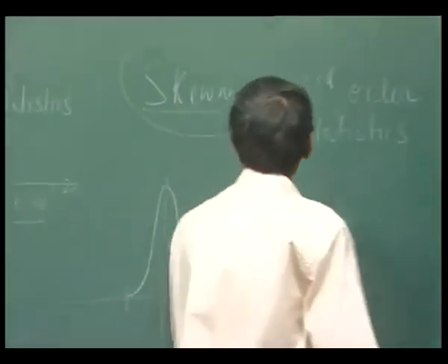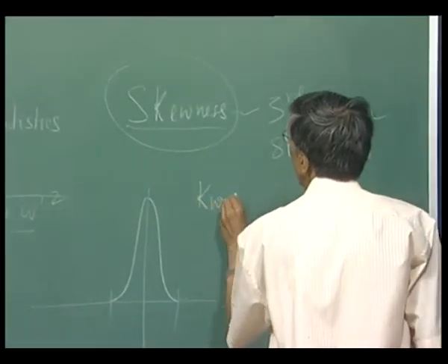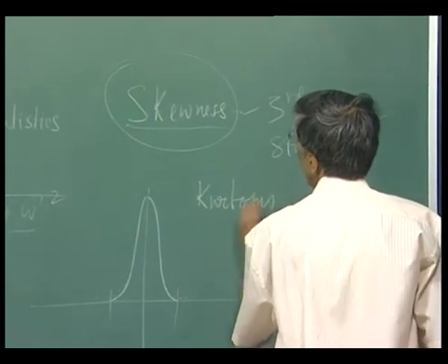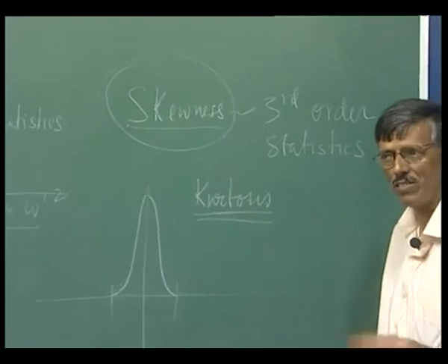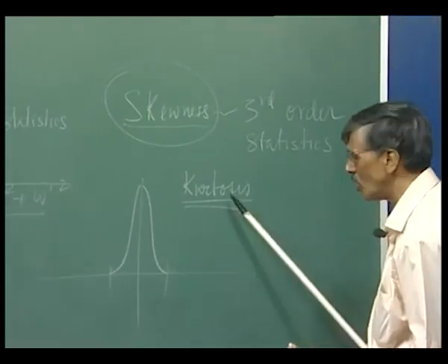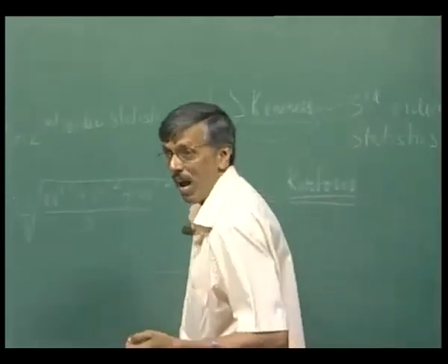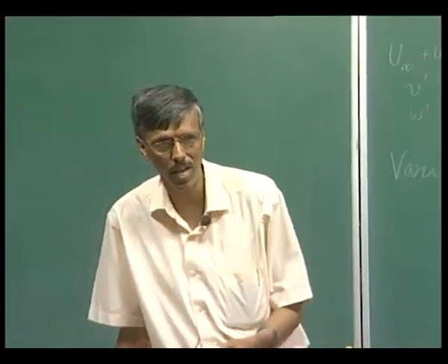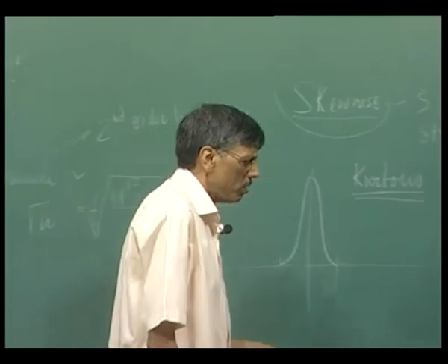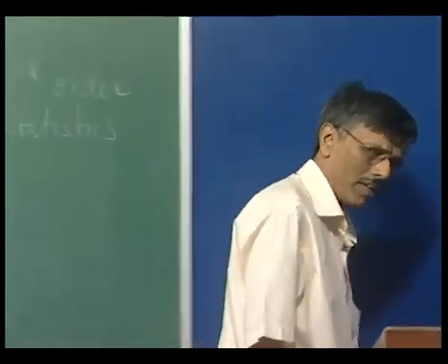So, we need to really worry about all this. While skewness gives you some kind of an instability, the kurtosis tells you what happens at high wave numbers, high frequencies. Kurtosis tells you about that, right. So, a computer generated random number cannot be a true substitute for free stream turbulence. This is what we did realize, and we did model it.